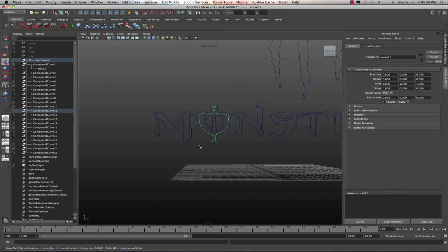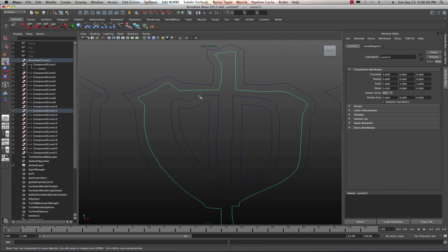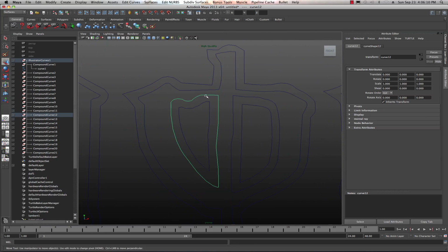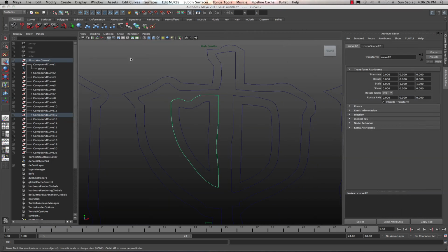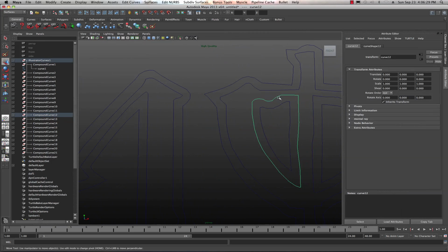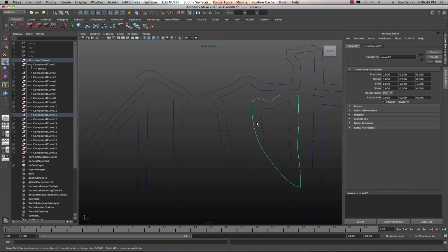So there we go. Now, next thing we've got to look at is a lot of times when you bring curves in, especially with a lot of different types of curves, they're raggedy, okay, and they're going to produce aliasing. So a lot of times when you come in to do a render, you'll notice that your edges and things like that look a little raggedy. And that's because we need to take these curves right here, and I'm going to show you what happens. Let's keep an eye on this curve really closely, okay? Because I'm going to come into Display and go to NURBS, and we're going to go to Fine, okay, and select that Fine. And when I do that, watch what happens to that curve, okay? You may or may not be able to see this very well on YouTube, but it just smoothed out that curve quite a bit. And that'll help with anti-aliasing, okay?